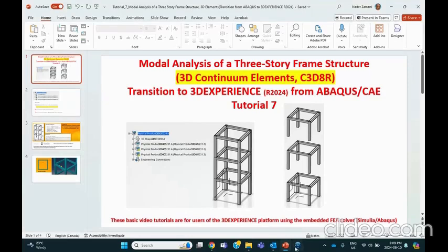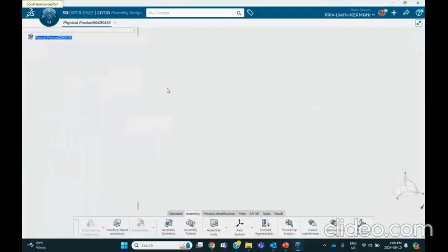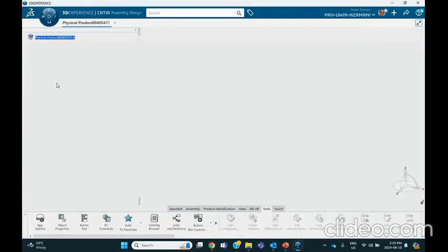We are in the 3D Experience platform. Immediately I save this thing. The first thing that I do is I insert a dummy part here, and its sole purpose is to have access to the axis system if I want the linear multi-instantiation direction to be picked. Now this was explained in detail in tutorial 18 that I referred to, and tutorial 17, so that's why I'm going to skip some of the unnecessary steps.